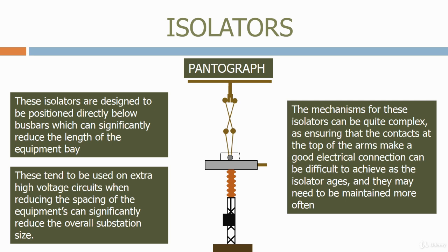The mechanisms for these isolators can be quite complex, as ensuring that the contacts at the top of the arms make a good electrical connection can be difficult to achieve as the isolator ages, and they may need to be maintained more often.